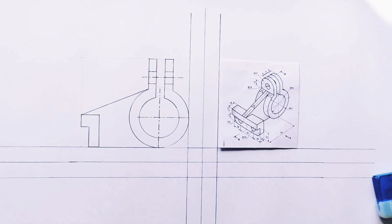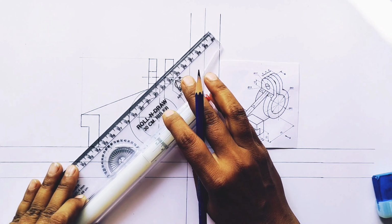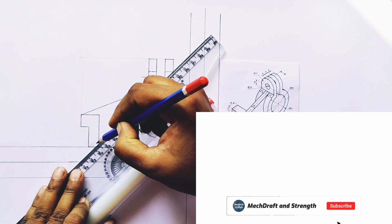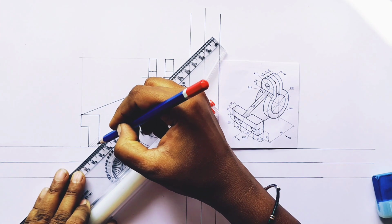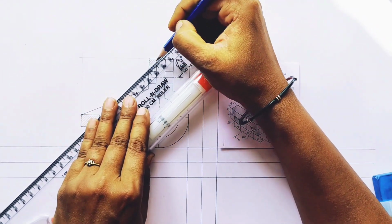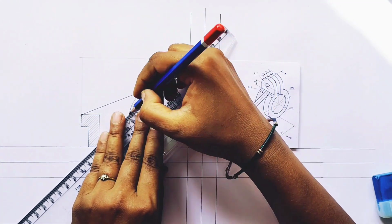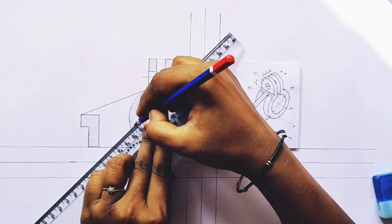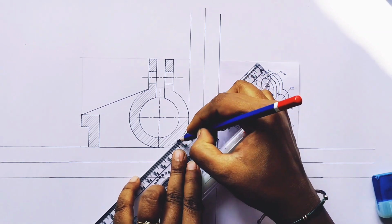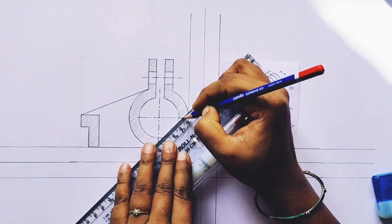Okay, so let's continue our front view. Here I am drawing 45-degree hatching lines. Make sure to maintain at least a 2 mm gap between each line. The hatching lines are given to the material that is actually cut by the cutting plane. You have to remember that, so you will understand where you have to hatch. Okay, hatching requires focus and control. So take your time, keep your lines even, and avoid rushing. That's the main thing. Patience will make your drawing look more professional.